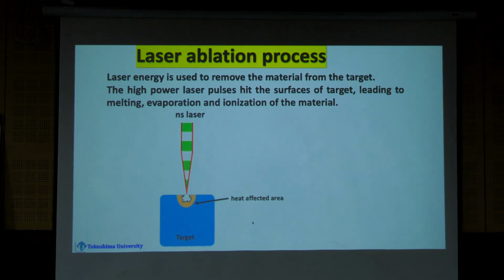This is pulsed laser deposition. Pulse means a 10 nanosecond pulse. Every 10 nanoseconds, one pulse is going on, so that phenomenon occurs in 10 nanoseconds. The plasma is created and vanishes within 10 nanoseconds, but this is a continuous process. This heat creates a shock wave.